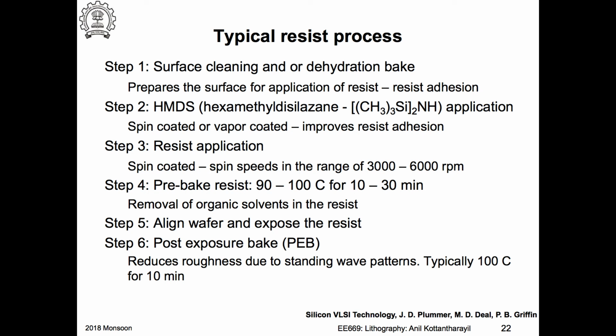But in some cases, dry etching using oxygen plasma is used, because the resists these days are organic materials, so you can burn the photoresist using oxygen plasma. Now the other thing that is used, if you can't remove the photoresist by these techniques, then you go for piranha solution.